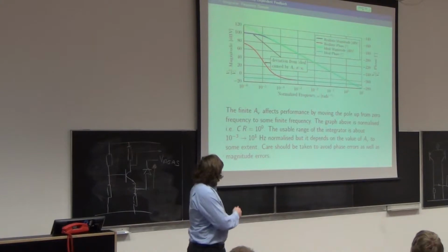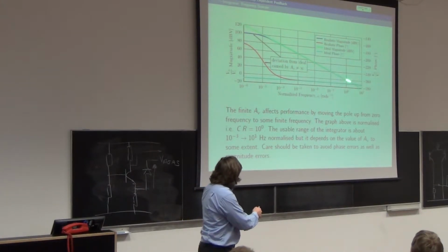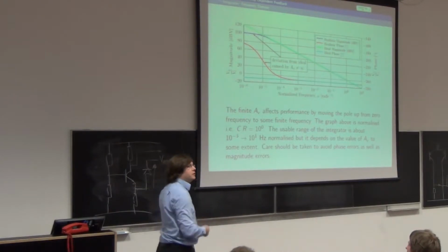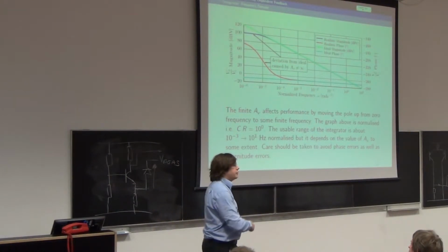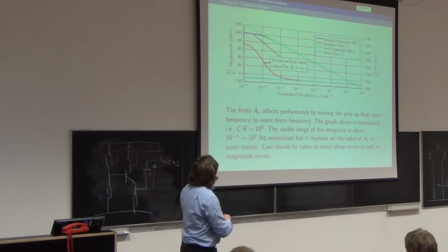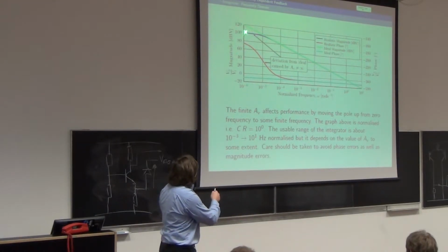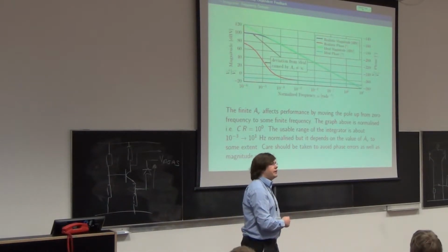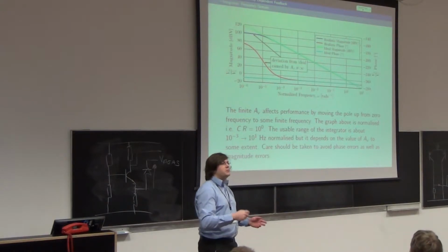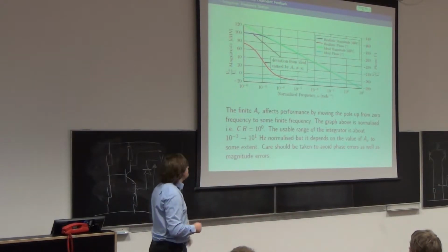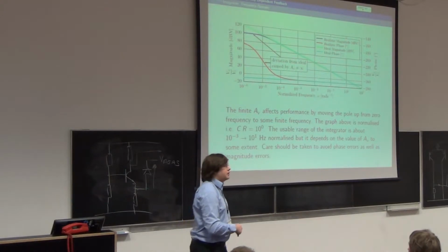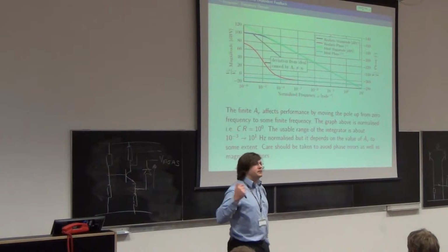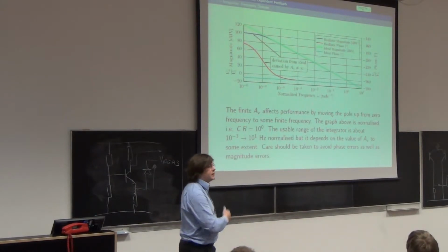So we have, green is that one, which is a straight line, and that's what we ideally like to happen. You could keep going back as far as you like into lower and lower frequencies, and it would always get higher and higher and higher. Actually, there is some point where the open loop gain becomes apparent, and when you get close to the value of the open loop gain, there isn't much open loop gain spare to perform the feedback functions. That is to say, the reducing of sensitivity to component variation, the changing input and output impedances, and all the other things that I said feedback does from ages ago.